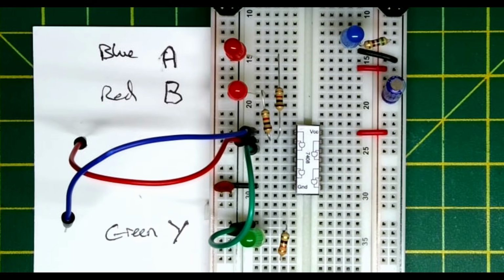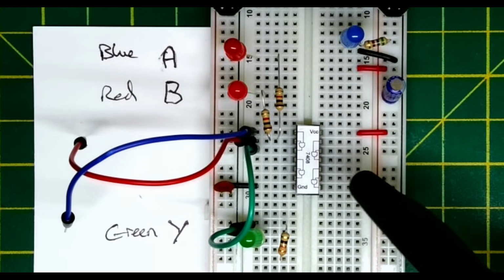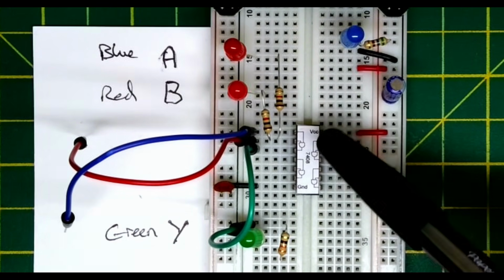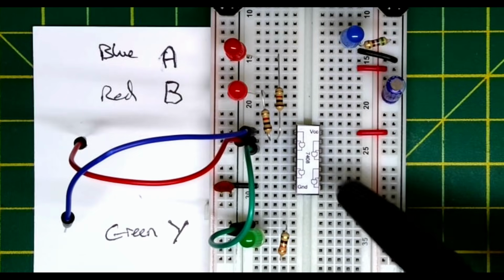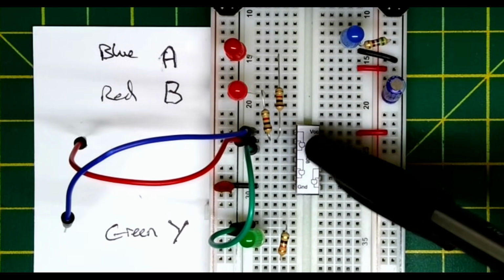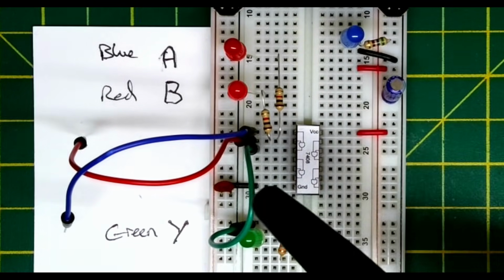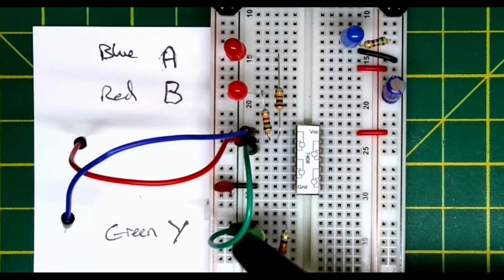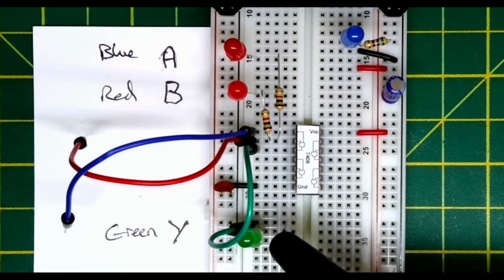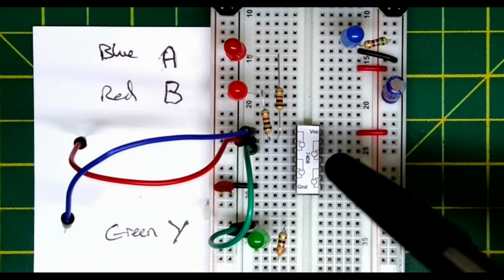Okay, so here's our simple test circuit. This is the 74LS08. This is our quad 2-input AND gate, and you can see the gate that we're going to be testing: pins 1 and 2 are the inputs and pin 3 is the output. The pin 3 output is just going to this green LED with a 330 ohm resistor, and because the output voltage there is a bit lower than 5 volts, this can be a little bit lower resistance value.